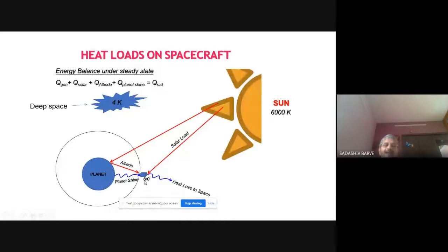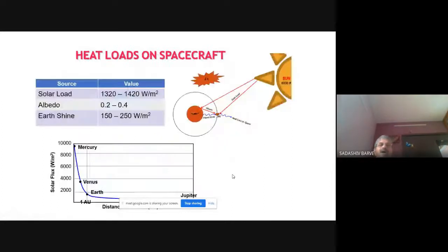So the satellite receives direct solar load, solar energy reflected from the Earth's atmosphere onto different surfaces, and the planet load from the object. These are the three different loads. All the external surfaces of the satellite receive them, and by virtue of its limited area, the temperature and its variation will take place. Again, I will come back to that load.